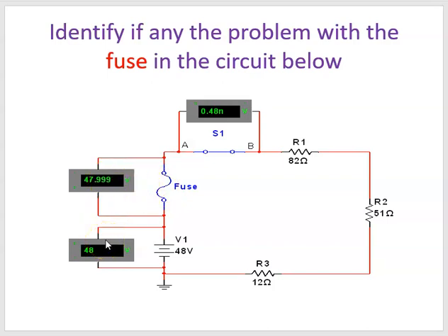And we know from the properties of an open circuit that one of them is that we'll measure the supply voltage across an open component or device. This tells us that this fuse must be open.